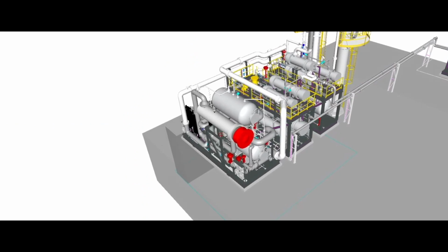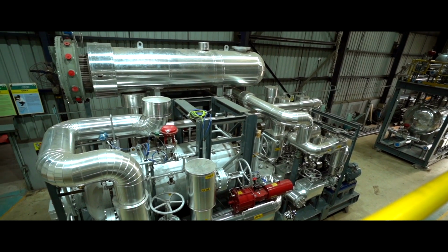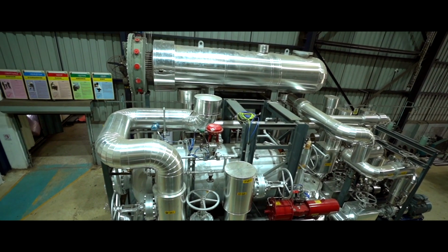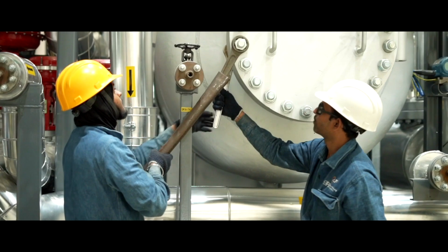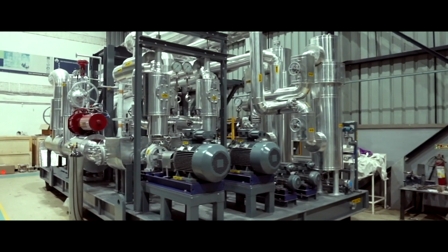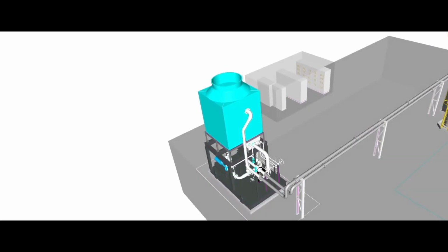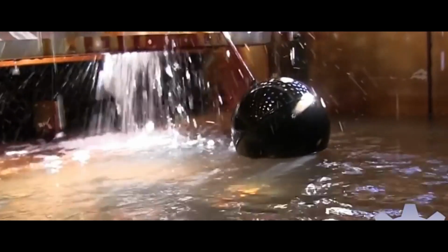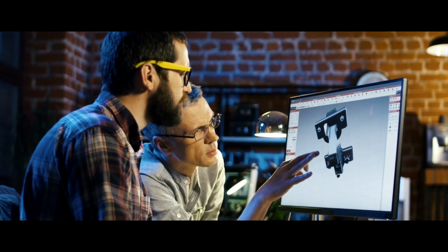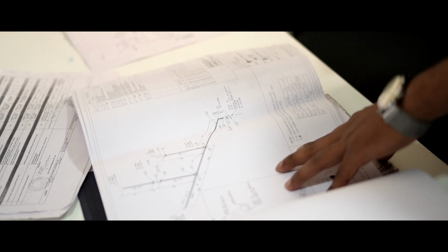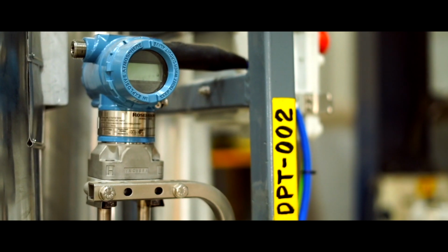The entire residual heating process is done by Dowtherm A using a 2.2 megawatt electric heater, specialized circulating pumps, duplex hot oil filters, expansion and drain tanks. These components are housed in the hot oil skid. The cooling system with cooling tower and circulation pumps is mounted on the cooling tower skid. This kind of design engineering is a great example of interdisciplinary coordination involving 3D modeling, static equipment design, piping, electrical and instrumentation, automation and control.